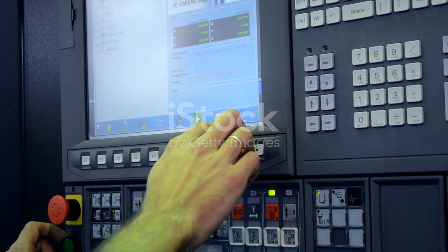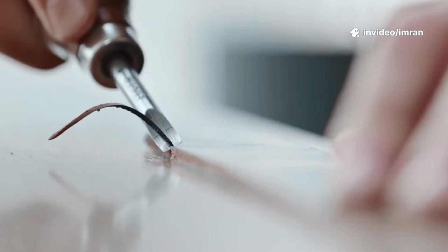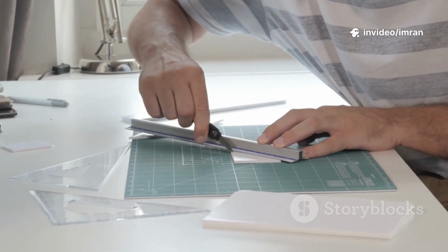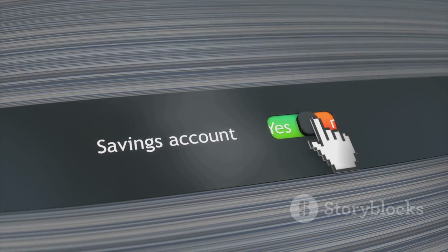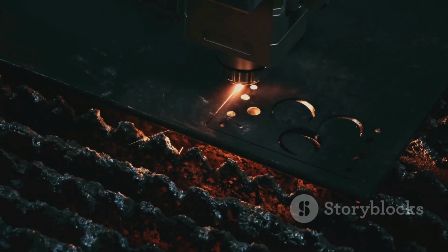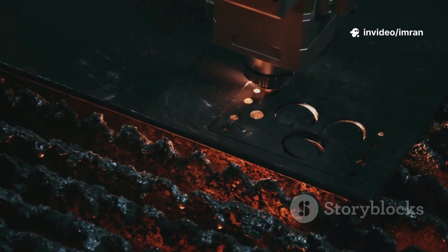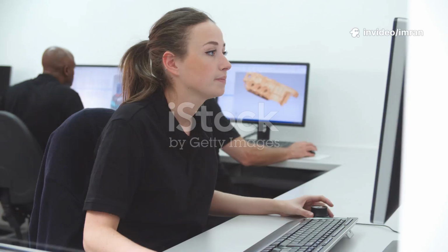The Trim command is a powerful tool for cleaning up overlapping objects. The command alias is TR, or select the icon on the ribbon. In modern AutoCAD, Trim operates in quick mode. Simply click the segment you want to remove. Use a fencing selection to clean up multiple lines at once. An object can only be trimmed if it intersects with a cutting edge. Practice trimming overlapping lines and circles.